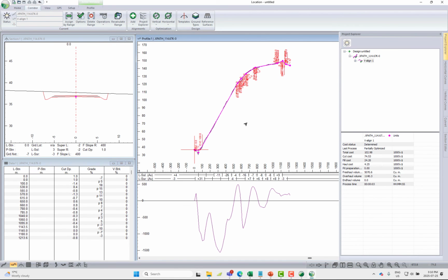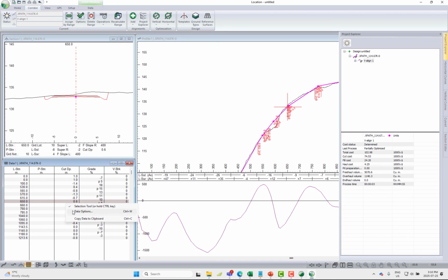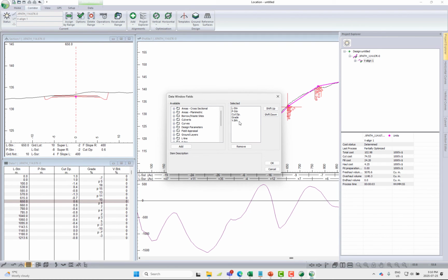Yeah, 167 cubic meters. So within a matter of 19 minutes, we've gone through an introductory PowerPoint. We have created an initial generative alignment design using Path Explorer AI, and now we've been able to really quickly optimize that design even further by adjusting the vertical. We can get all the different volumes for this particular project and outputs here in RoadEng. You can also send this out to another design software if you're working with one.